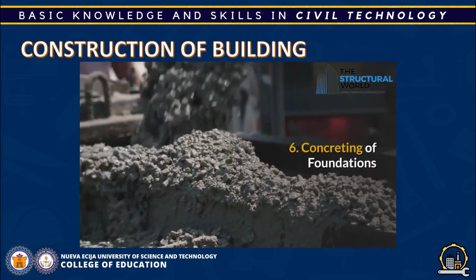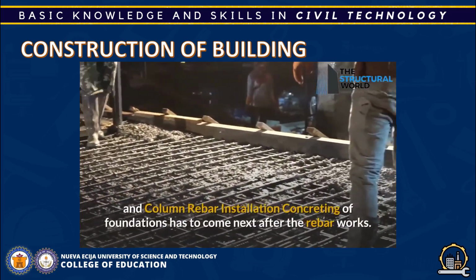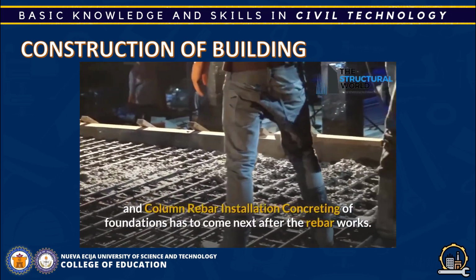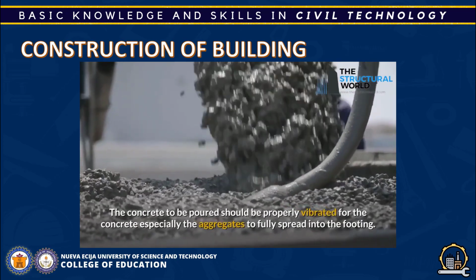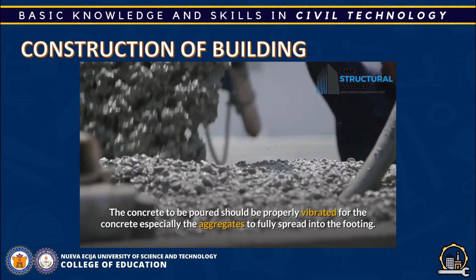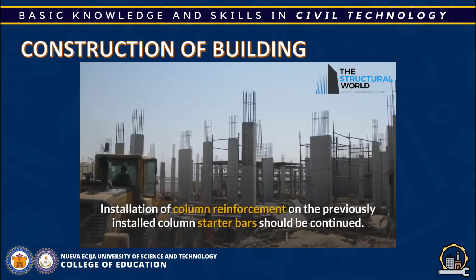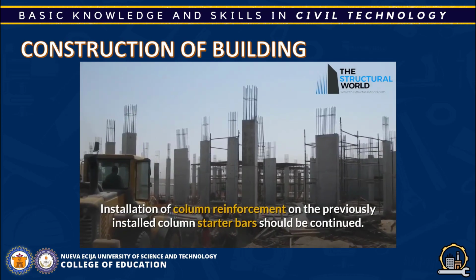6. Concreting of foundations and column rebar installation. Concreting of foundations has to come next after the rebar works. The concrete to be poured should be properly vibrated for the concrete, especially the aggregates, to fully spread into the footing. Installation of column reinforcement on the previously installed column starter bars should be continued.